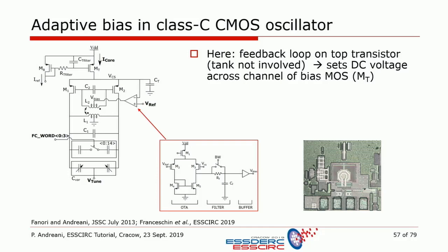In this case there's a feedback through a transformer, and then we have a low frequency feedback to stabilize the DC voltage of the gates of the differential pair.